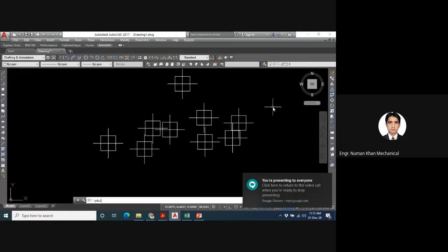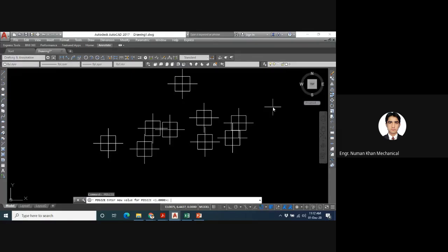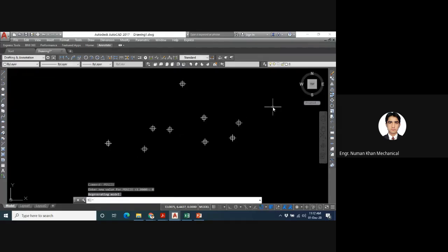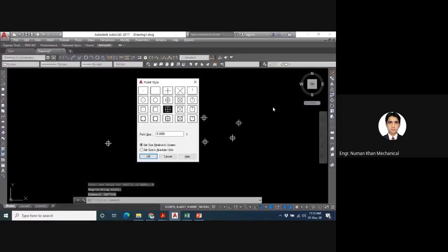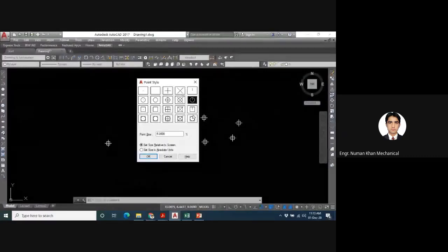मैं पीडी साइज लिखता हूँ, एंटर करता हूँ, मैं इसको 0 वैल्यू देता हूँ, ये ऑटोमेटिकली आपके एक्चुअल साइज पे आ जाएगा। अगर इसको चेंज करना चाहते हो, you can change it 2, 3, 4, it's up to you. एक विंडो से करने के लिए इसके लिए कमांड है DDPTYPE. एक विंडो ओपन होती है और यहाँ से भी वो चीज आप सेलेक्ट कर सकते हो, instead of knowing the value, अगर ये कमांड आपको पता हो.